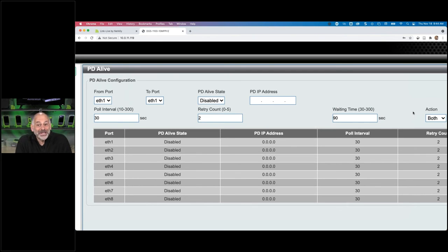So we'll actually reset the device. What we're going to do is come over here, and let me move my camera before we do. For this webinar, I bought a PoE splitter. What this PoE splitter does is it takes the PoE and splits it out to 12 volts. It splits out a gigabit Ethernet connection, but it also splits out 12 volts, and it will run up to 4.5 amps of 12 volts.